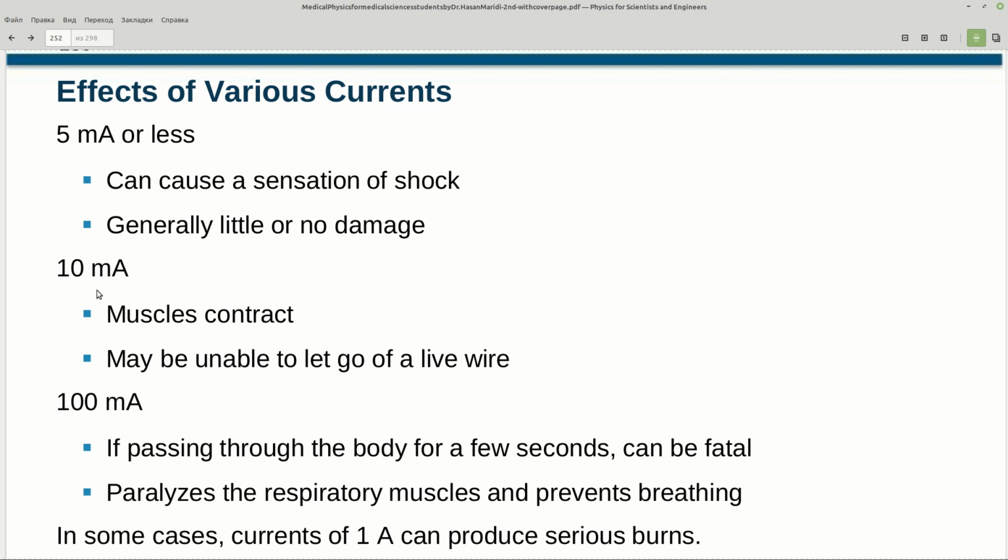In this situation, the live wire has come into contact with the drill case. As a result, the person holding the drill with two arms acts as a current path to the ground, and this person receives an electric shock.